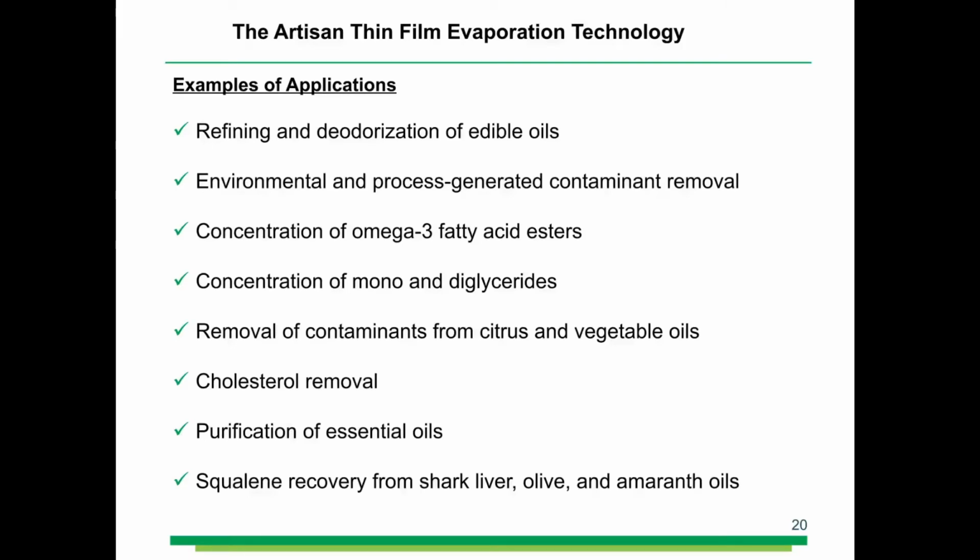Other applications of this multi-stage thin film technology are in the concentration of mono and diglycerides that are widely used as emulsifiers, the removal of other contaminants from oils like citrus oils, also in the recovery or removal of cholesterol from animal fats, the purification of essential oils, and also the recovery, which is not listed here, of antioxidants, and more recently, the recovery of squalene from shark liver oil, olive oil, and amaranth oils.